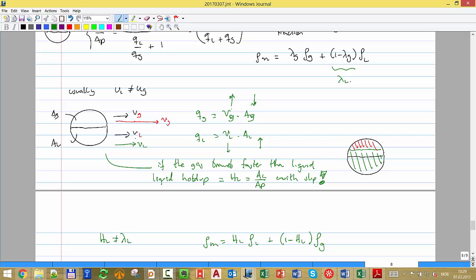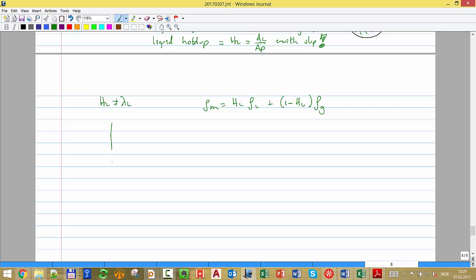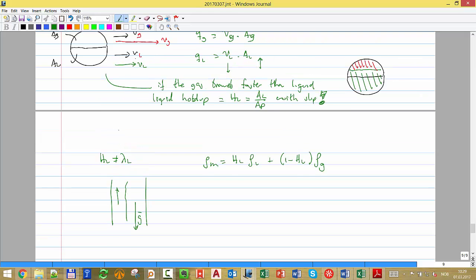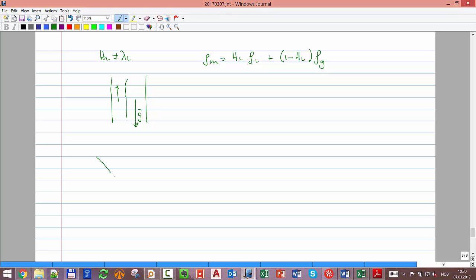One example when the gas travels much quicker than the liquid is when it's flowing upwards. In upwards flow, the gravitational forces pull the liquid down much harder than the gas. So that causes a slip where the gas goes much quicker, and in that case you will have that condition. But if you have downwards flow, let's say you are going down a pipeline, in that case gravity is going to help the fluid. So what's going to happen then?